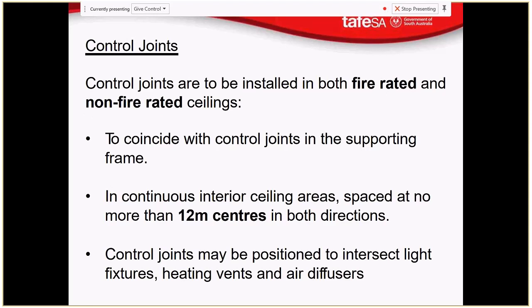So our standard joint is going to happen like this. We've got a ceiling joist happening here, and very wonky plasterboard with a joint happening there. We've got our recessed fixings with our plasterboard screws, so bugle ends on those screws.